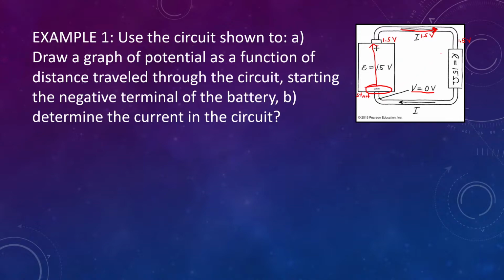We then hit the resistor. So now we travel down the resistor. Well, remember, resistors drop your potential. And so in this case, we're going to see a voltage drop back down as we get here. So one way to look at this is that if your potential is 0 at this part of the wire, your potential also has to be 0 here at the bottom part. Then we traverse the bottom wire at 0 volts before we hit the battery again, and this cycle continues.